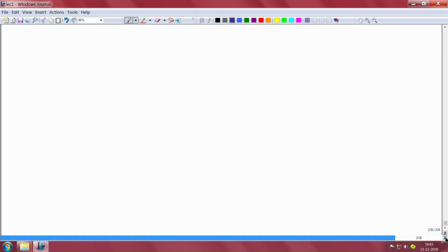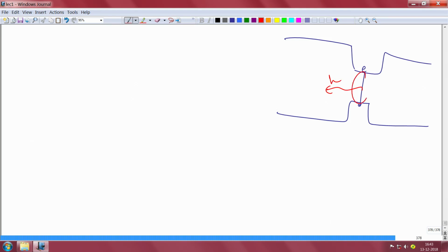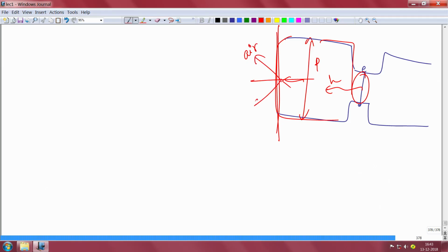Even if you have a wide band gap semiconductor in a PN junction, when the electrons and holes recombine, the energy of the emitted photon is less than the band gap of the p type or n type layer. So the photon will not get absorbed in this layer. That is different from this refractive index issue. Refractive index is, this is air, this is the semiconductor. So at this interface it will get refracted, no. So total internal reflection will basically limit it.